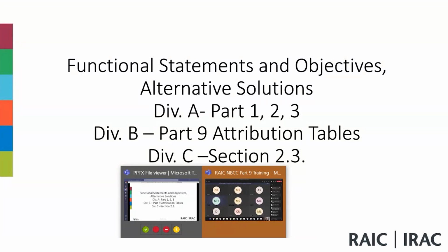So you guys followed on that. 9.10.7 is talking about steel members. If structural steel members used for construction are required to have a fire resistance rating, they need to be protected to provide the required fire resistance rating. But 9.10.8 talks about the fire resistance rating of structural elements, floors, assemblies, basically floors, mezzanines, and roofs, and that applies to any type of construction, whether combustible or non-combustible. Okay, got it. Thank you.